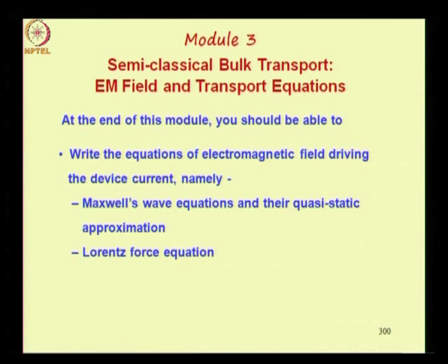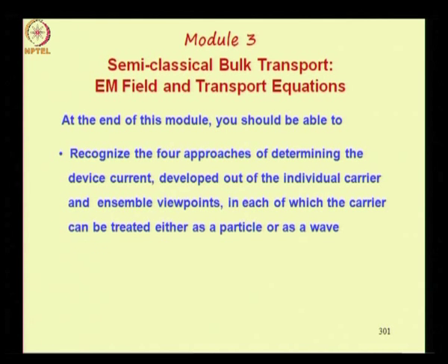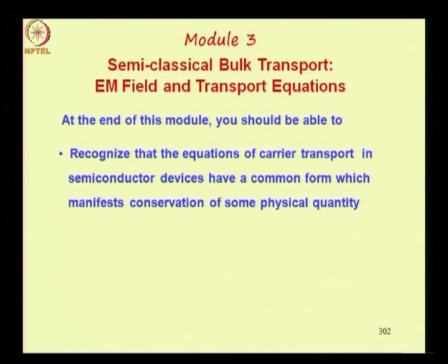So to summarize, at the end of this module, I hope that you are able to write equations of the electromagnetic field driving the device current, namely Maxwell's wave equations and their quasi-static approximation, and the Lorentz force equation. Recognize the 4 approaches of determining the device current developed out of the individual carrier and ensemble viewpoints, in each of which the carrier can be treated either as a particle or as a wave. Recognize that the equations of carrier transport in semiconductor devices have a common form which manifests conservation of some physical quantity.